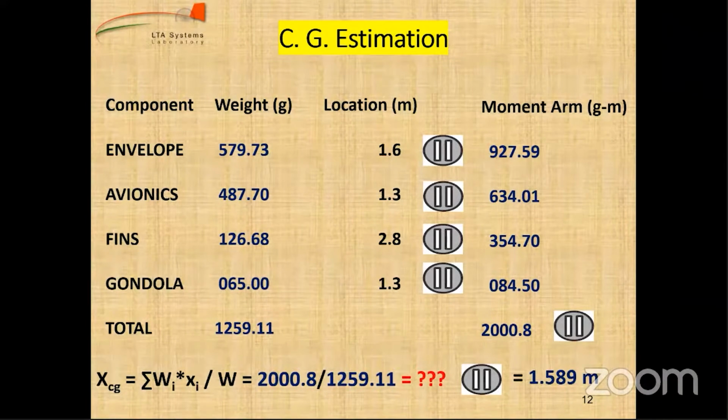Yeah, that's one way. But actually, ballast can vary in its mass. So dead weight you can actually vary, right? You can change its mass. So what we do is we keep its position fixed, because it's always much more difficult to have a variable location, but it's much easier to have a variable mass.